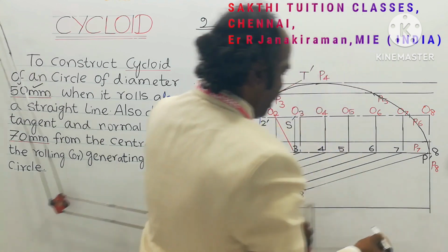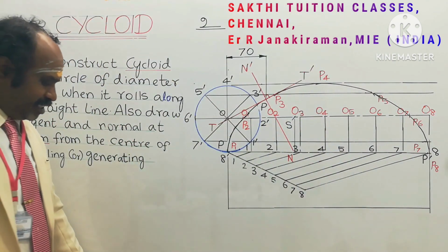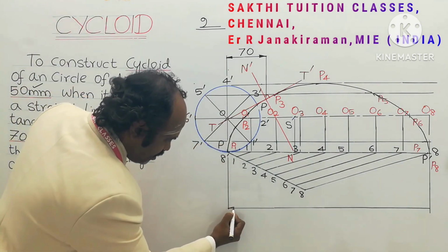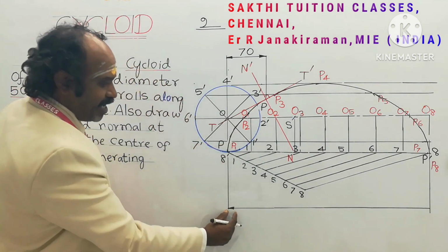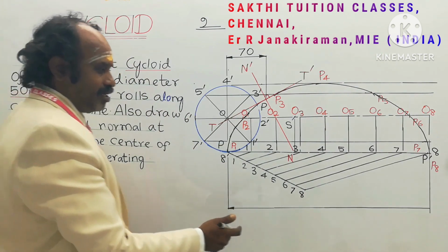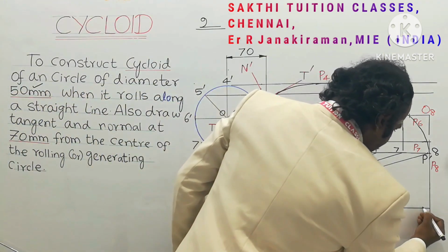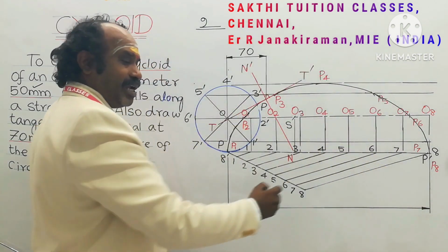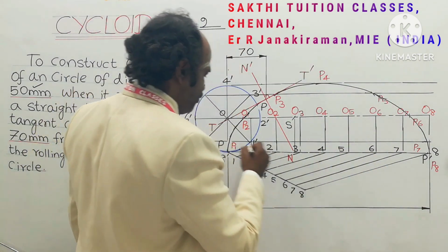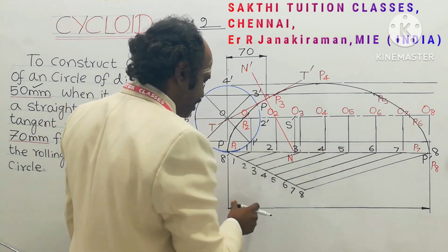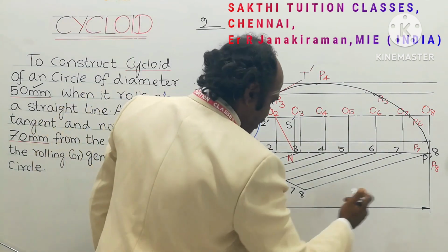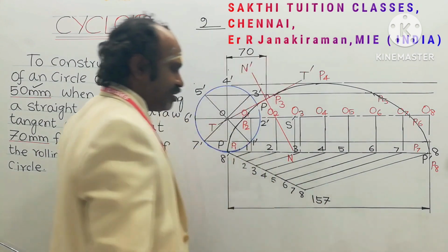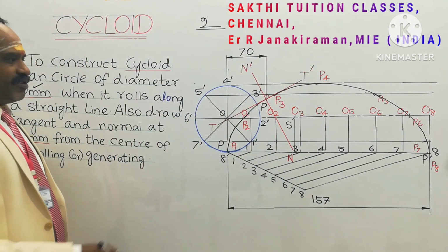Where this dimension line intersects with the extension lines, provide two narrow arrowheads. The length of the arrow shall be greater than the width of the arrow. Understand? So provide two arrowheads and shade them. At the center of the line, above the line, write the length of the line marked as P dash, which will be 157, parallel with this dimension line. The mm need not be written. And next is the circle.